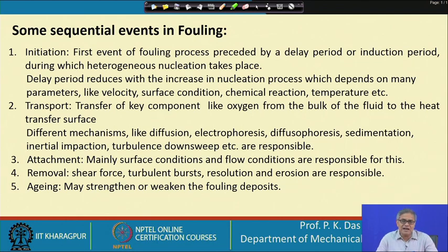What is getting attached may get removed also, due to shear force, turbulence bursts, or dissolution in the fluid stream, and then erosion. So, what is depositing may not permanently stay on the surface, because there could be removal. This is a dynamic process: there is deposition, there is removal.